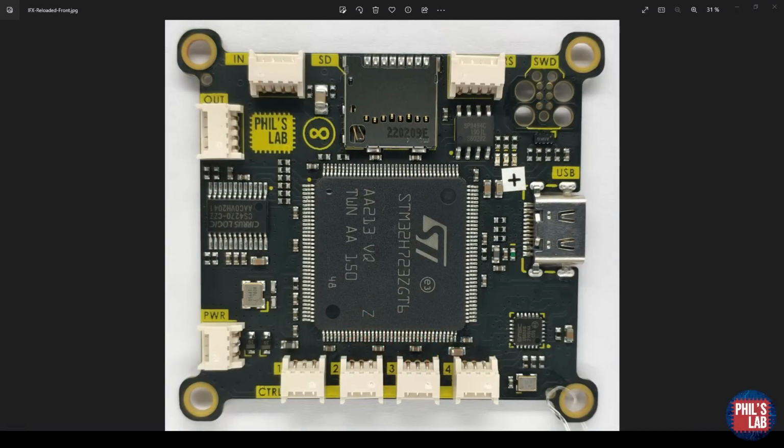For the live implementation, we'll be using this custom DSP board I designed specifically for audio applications and videos such as these. We have an STM32H7 microcontroller, an audio codec which contains ADCs and DACs, various other peripherals, as well as a USB connection which provides data and power, and serial wire debug for programming and debugging.